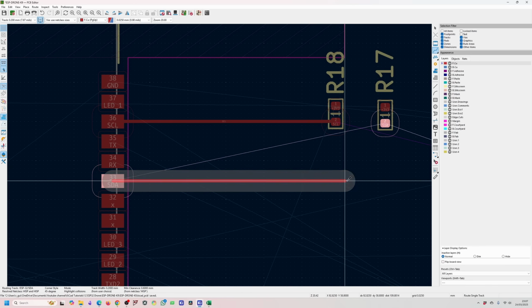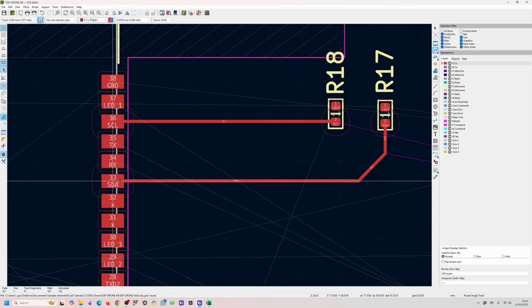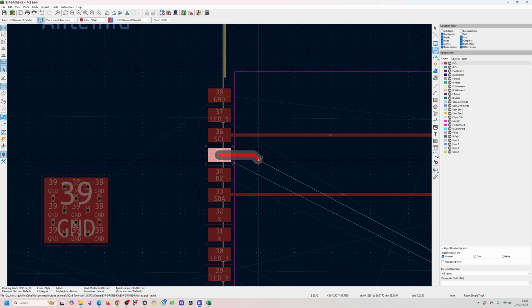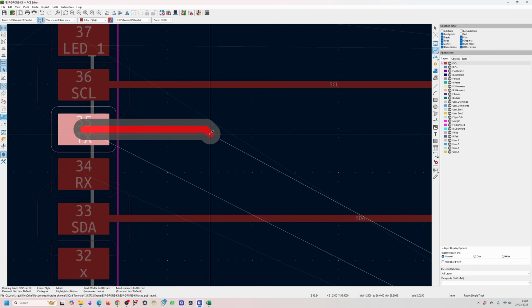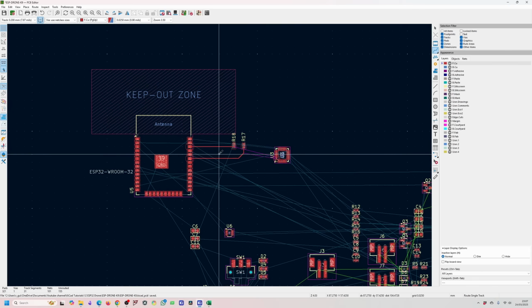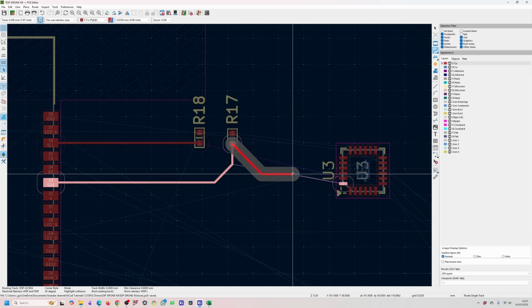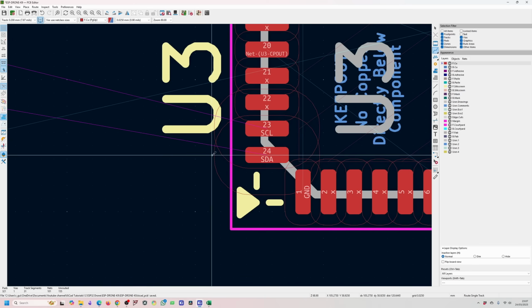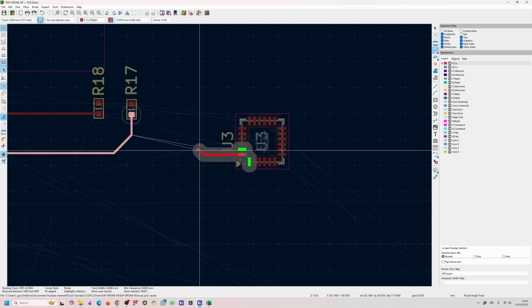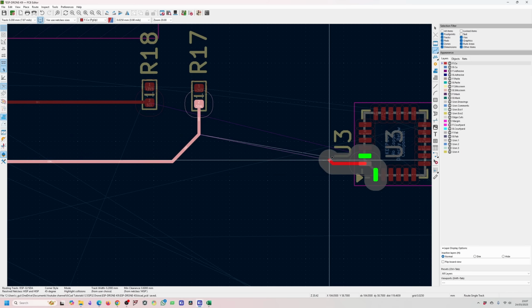Now you can see over here that we've got our 0.6 clearance basically for this track. And if we were to do another track that has the default net class, that clearance is less. So let me just click on this pad and you can see that the net class for this is default and the net class for this is high speed, which gives you the different rules managed automatically. Now, when we need to route this track, we can basically make sure that the clearance is good. And obviously you're going to have problems when routing this, but that's okay because we are doing that intentionally.